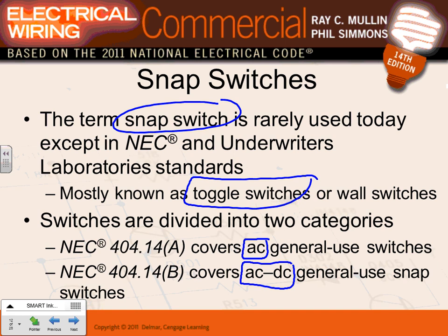We're looking at the AC here, but if you are to break DC, anybody know why DC is an issue when you break it? We don't have a lot of DC, but with photovoltaic systems coming, when you break DC, the arc of a DC is more dangerous than the arc of an AC because there's no impedance. The only impedance is the resistance. There's no XL. So remember, when you break a DC circuit, it's more dangerous; more arc comes out of breaking a DC circuit than out of breaking an AC circuit.